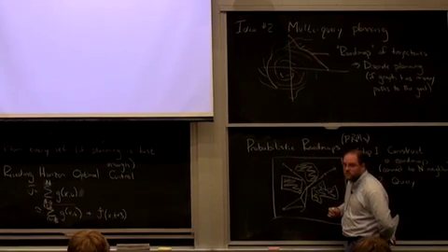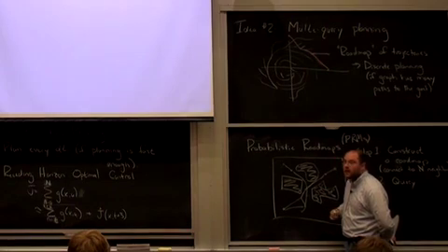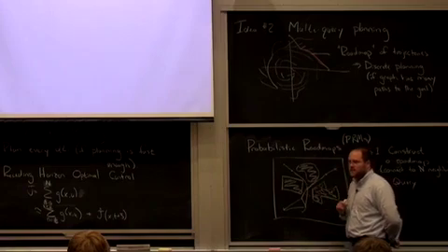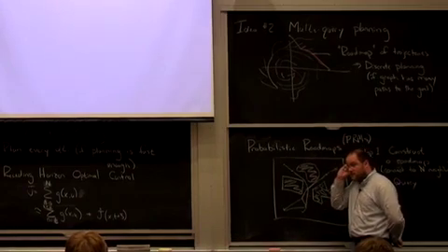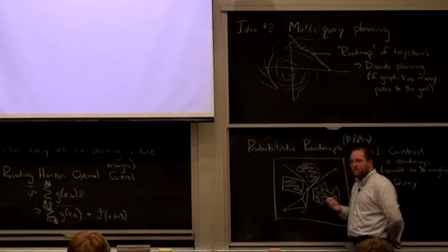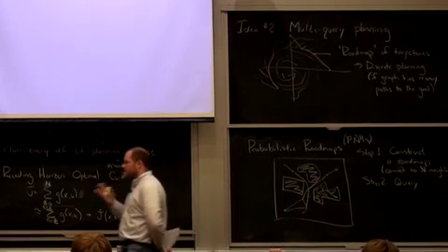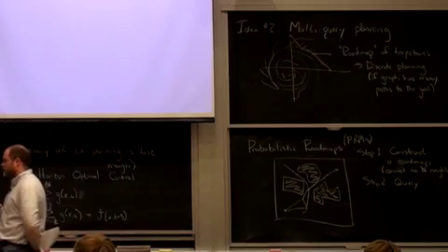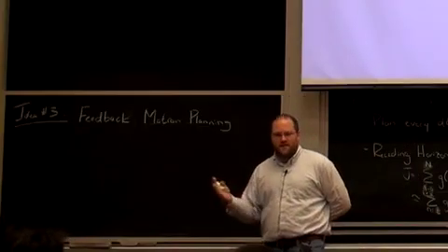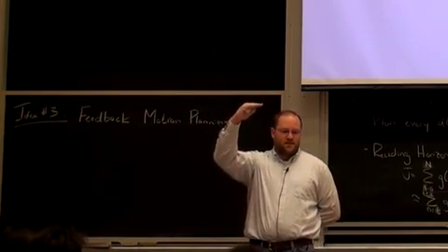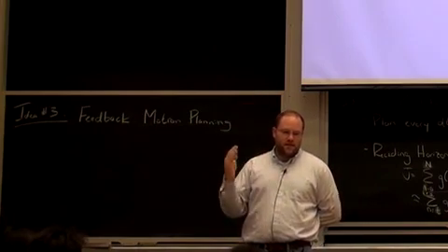So you're worried about the noise? I'm worried about noise, right? It's feasible for me to walk along the side of a cliff, but I wouldn't want to be bumped, right? If I know I'm going to be bumped, then I pick a different path, okay? So you could imagine ways to try to make the planning process more robust, let's say: don't use your full torque limits, use 90% of your torque limits. That's a good idea, that'll help.